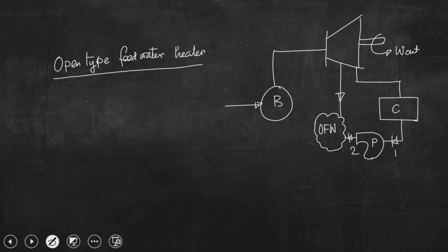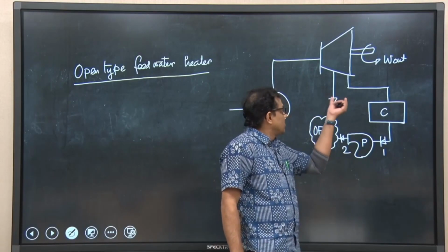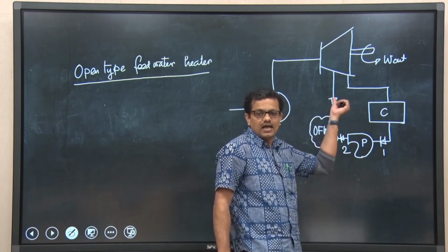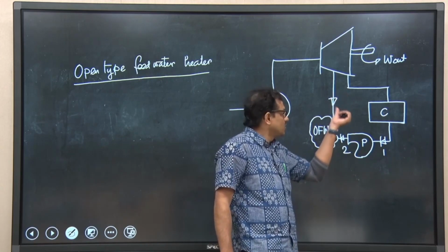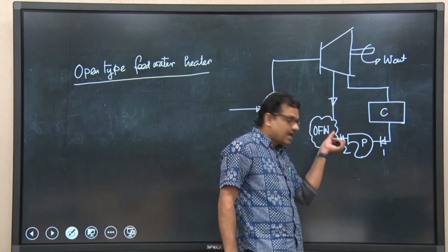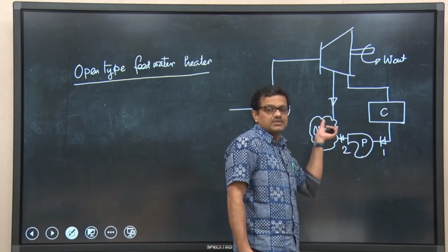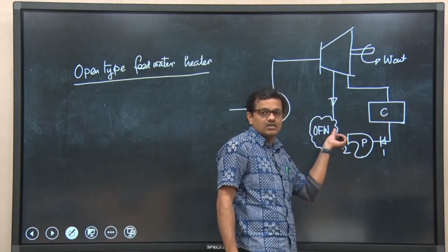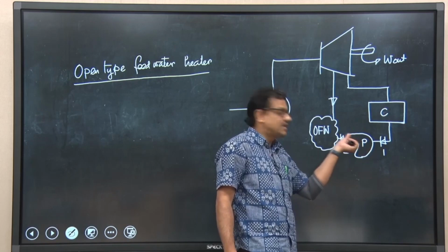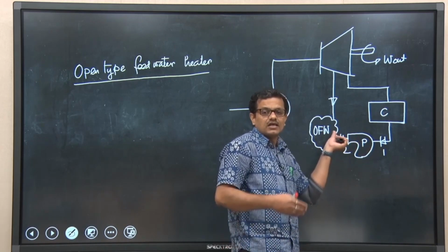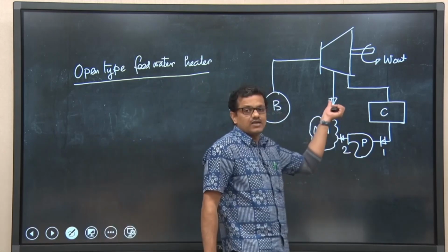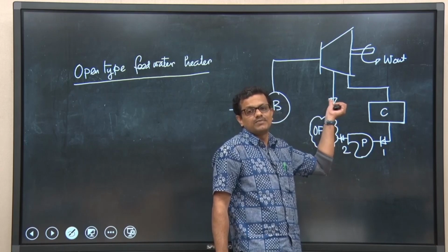Okay. So, now you have studied fluid mechanics, you know that the 2 streams are coming, and one stream is basically steam which is at high temperature and the pressure is also high. So, if we need to have efficient mixing of these 2 streams, we cannot directly take the condensate into this device, because the feed water which is taken to this particular device shall have a pressure equal to the pressure at which steam is extracted, otherwise mixing will not be efficient.